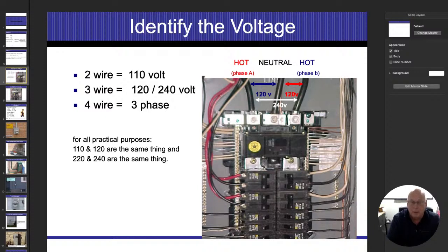So if I'm flowing 100 amps on the right side and I'm only flowing 50 amps on the left side, that means I'm still going to have 50 amps going down the neutral. I have to bring that imbalance back. The first 50 will cancel each other out, and then whatever's left over will go down the neutral. So the only way that I can even get up to 100 amps is if I have 100 amps flowing on one side, 0 on the other, and that's going to allow me to have 100 amps flowing on the neutral wire. Then as soon as I start adding amperage to the left side, that brings down the neutral. They're going to cancel each other out.